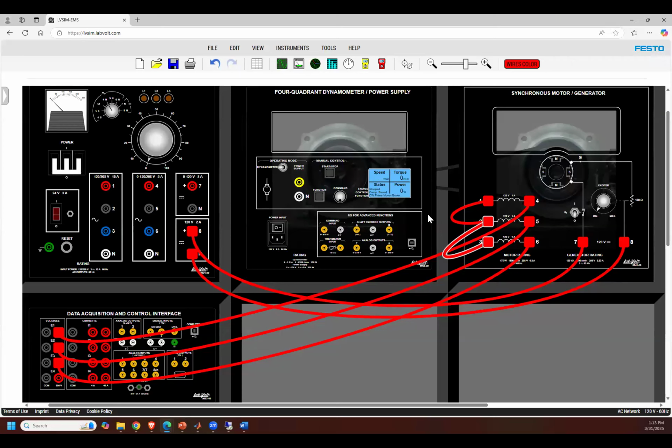I would think a Y. You built me a Y connection. What if I actually wanted a delta? Oh, well, that complicates things a little bit. Right. And I'm not saying we need to make this Y or delta. You can pick whatever you want. I'm just saying if you wanted a delta connected machine because you wanted your line voltage and your phase voltage to be the same, this ain't going to work. But we'll make it a Y to make it easy.